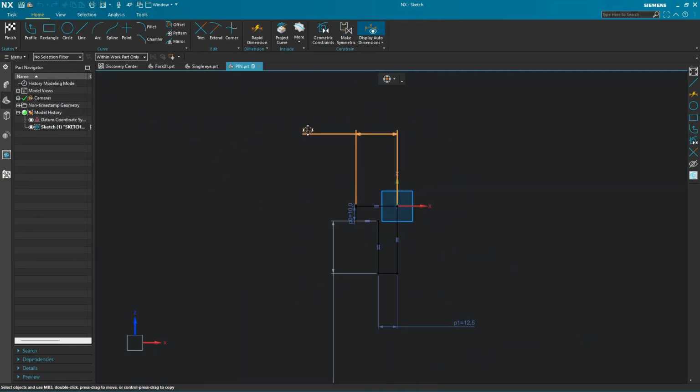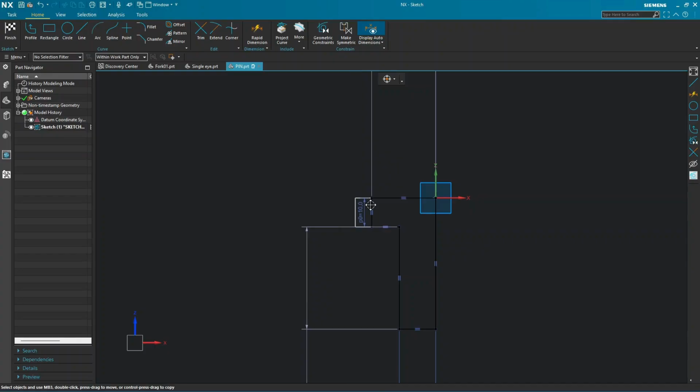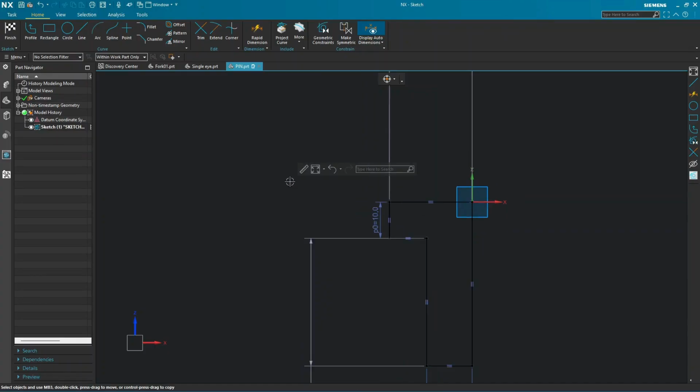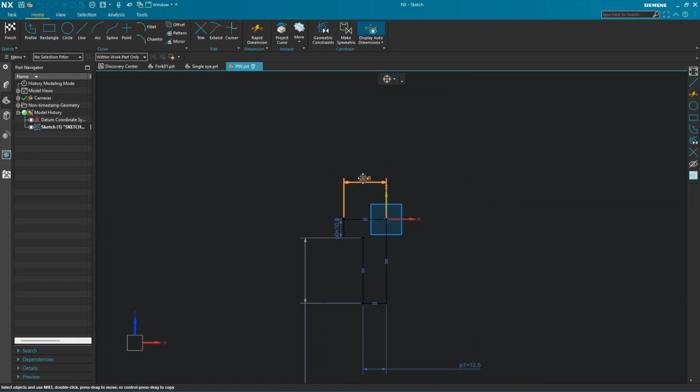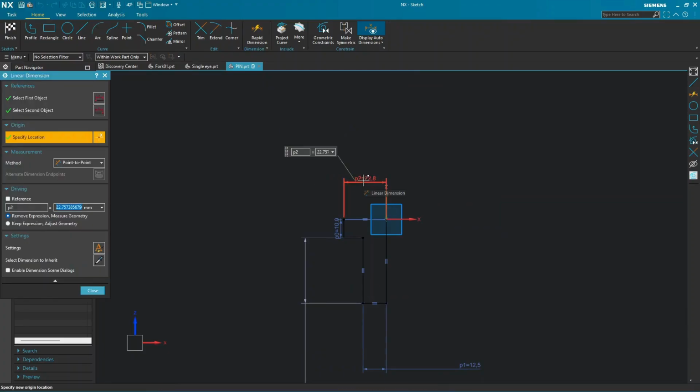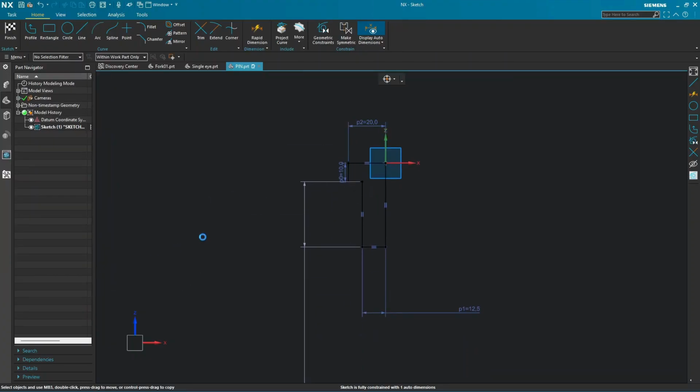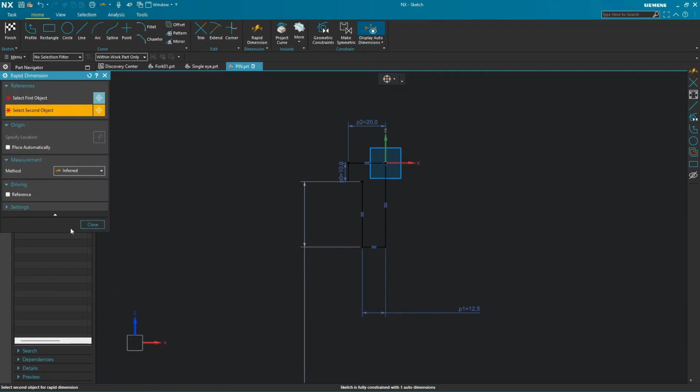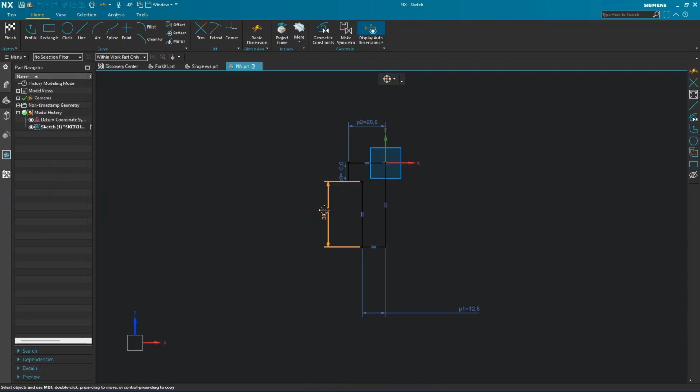To restrict axial movement and improve strength, I add a collar on one side of the pin. This collar rests against the outer surface of the fork arm, ensuring the pin doesn't slide out during operation. On the opposite end, I prepare a small taper pinhole or locking slot, which will be used later to secure the pin in position during assembly.